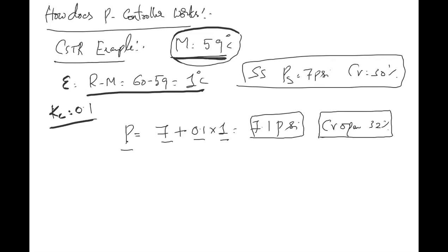So let's say this is 60 degrees. It drops because of some reason to 59. Now you are receiving a pressure signal of, sorry, the valve should close. The valve is 28%. The control valve closes to 28%. Then this sends less cooling water, and that means it will come back. Here there is a question whether this 28% is sufficient to bring it back to 60 or not. But this is how the response goes. The system is at 60 degrees, drops to 59. Since you closed the control valve, it takes a reverse direction and then settles somewhere.